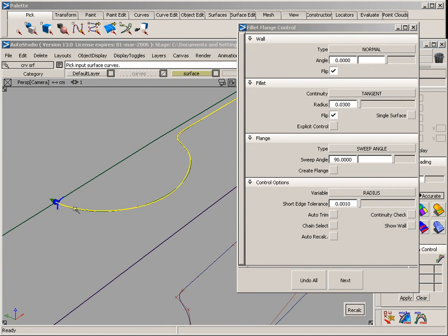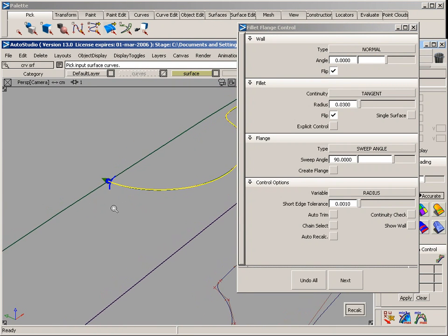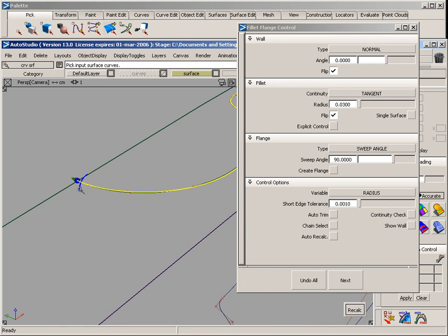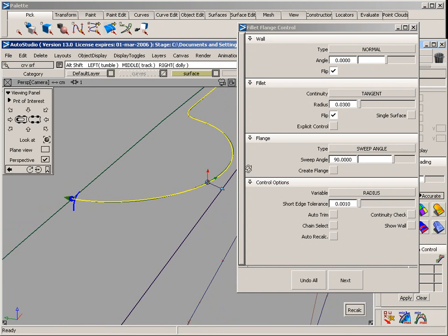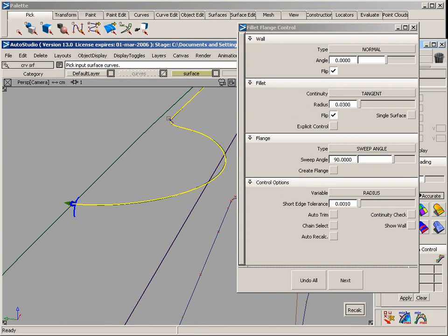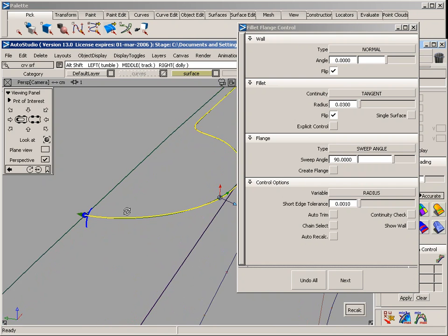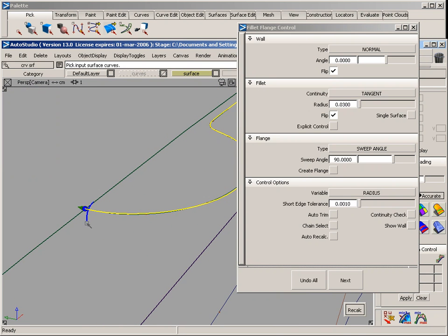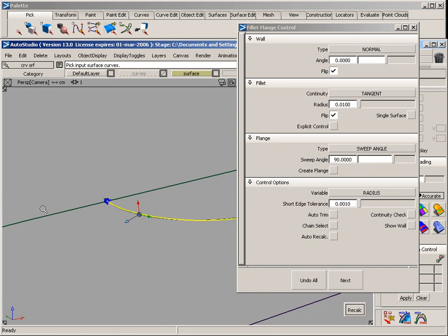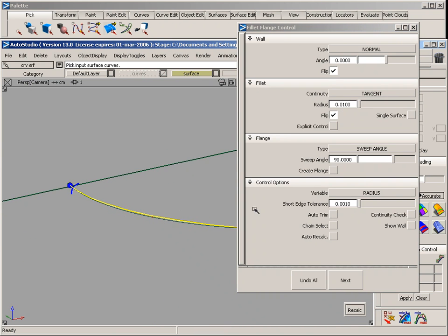I would click on this edge, and I would choose a much smaller radius than the one that you see here. The reason being is, if I'm looking at this bend over here, this one might cause some problems, same as the one over there, and also the transition over here. So I want to use something much more subtle than this. So for this I'm going to use 0.01. It's a very small one. Zoom in here, you can see it. And let's give this a shot.